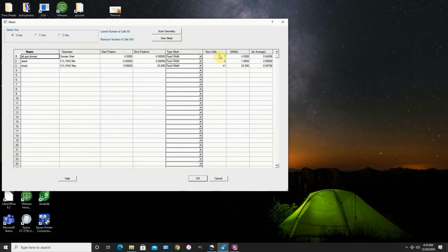And I think 7 is a good number, but what we want to do is to use a variable grid length, and we'll use a negative direction power law, which kind of stretches the coordinates in the negative x direction, and it starts from a finer grid, which we're going to put here on this stack. And for the stack, we're going to use 5 cells across it.